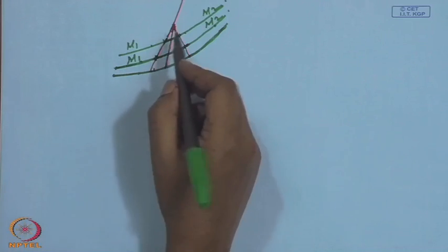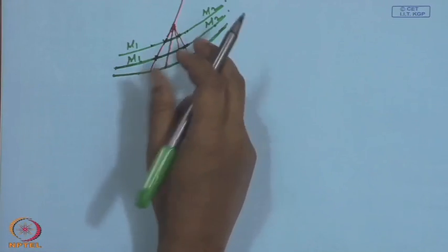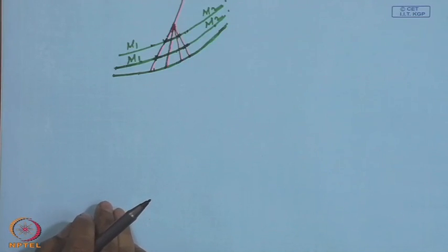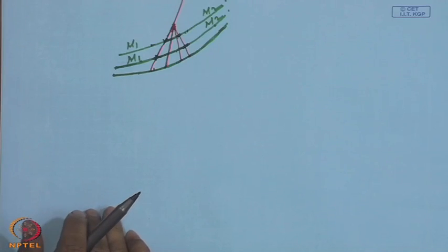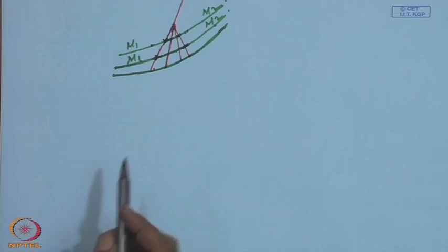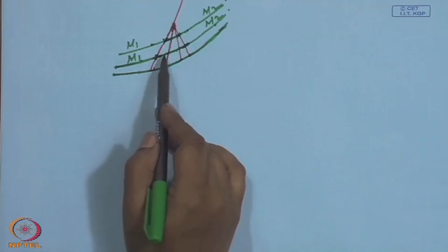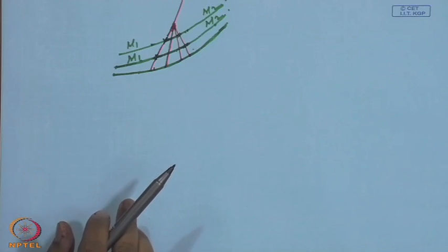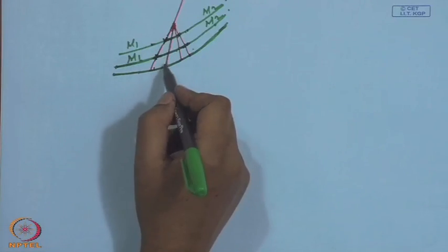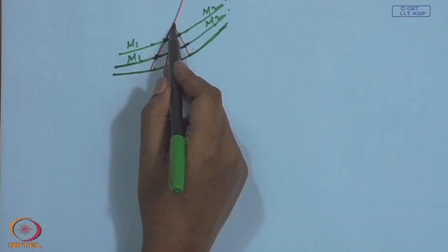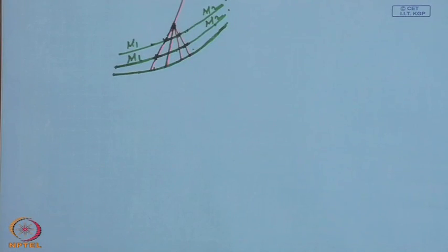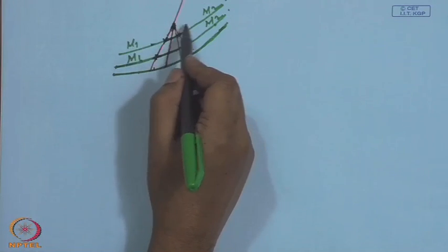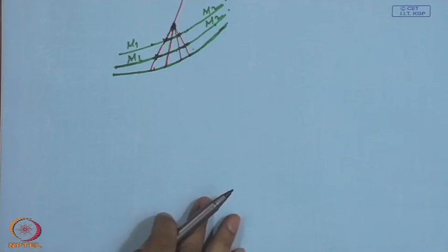That is, on this streamline the changes are occurring over a smaller distance. Consequently, the gradients of velocity, temperature and all other flow parameters on this particular streamline are much higher than on these streamlines. And at this point of intersection where all these Mach lines are meeting, it simply implies that this change is occurring over almost zero distance and the gradient is infinitely high.